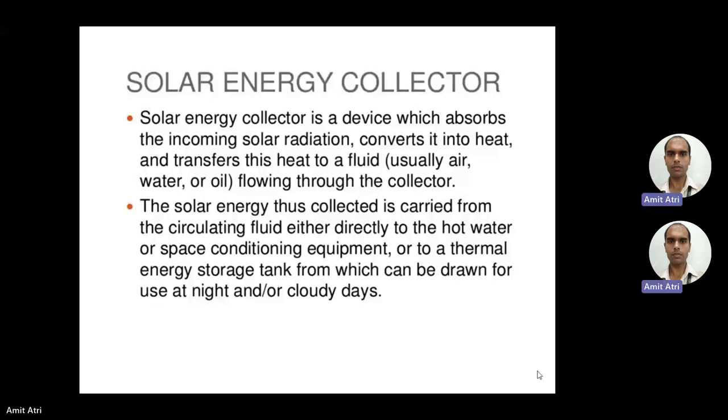The medium could be air, water, or oil flowing through the collector. The sunlight falling on the collector produces heat, and through this medium or fluid, that heat is collected and transferred to some other medium for some task to be performed, or to store the heat.